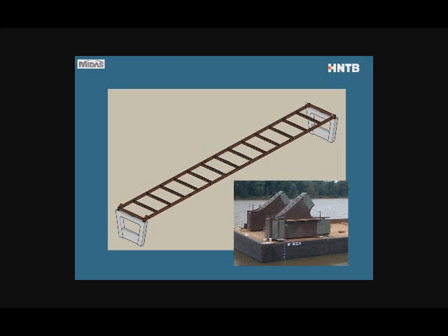Those are very complicated elements. They're quite difficult to design too, because this is where the arch rib, the tie girder, and the end floor beam all come together. And you also have to design for bearing replacement. So the knuckle joint sits on the bearings, but when you have bearing replacements, you actually have to put in some jacks to take the load off the permanent bearings, and so that's another tricky load case that exercises the end floor beams quite a bit.